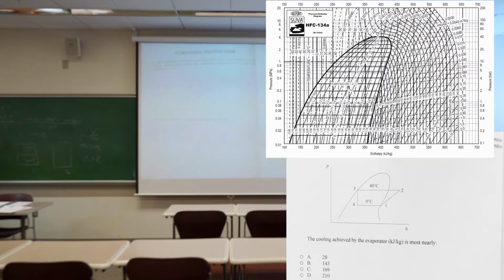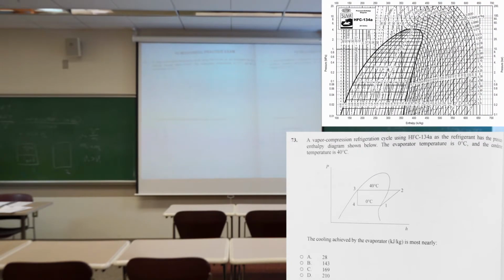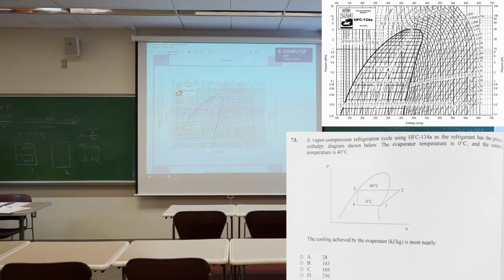So on the handbook, the steam table is provided in table form. However, if you want to find properties for the refrigerant, that is the table you are looking at. This is that table. For the refrigerant R134A, the handbook did not provide a property table, at least the 2013 version.